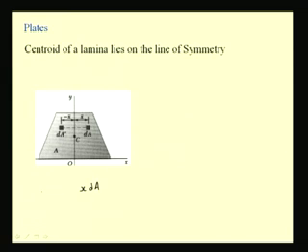and we know that we define the centroid x bar, and if A is the total area, as the sum of this value x dA for the entire region. So, we see that if symmetry exists for this object, then for every element dA which is at a distance of x from this OY, we have a corresponding element dA prime which is at a distance of minus x.